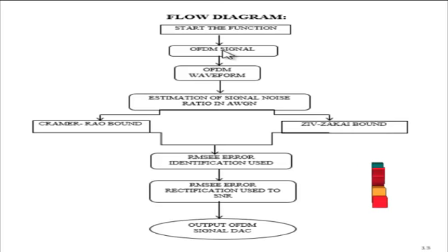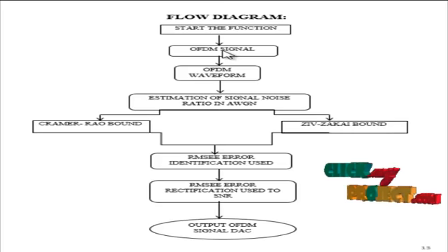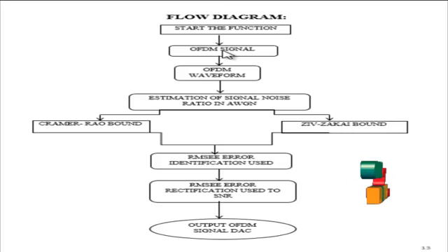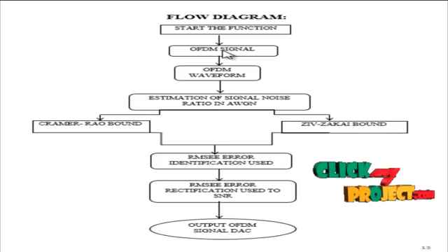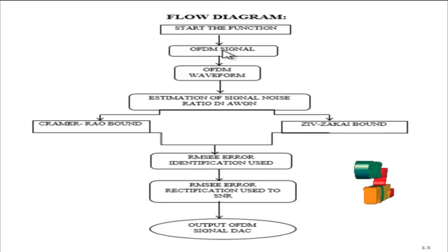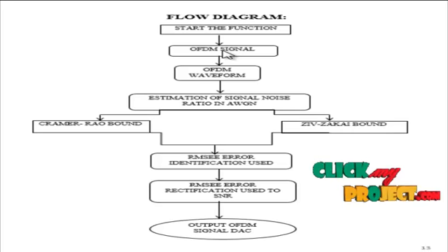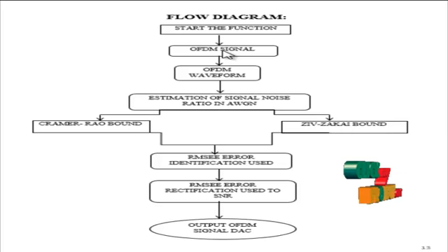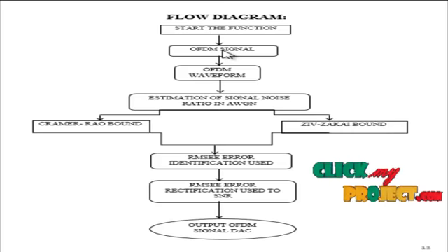The ubiquity of this communication technique has determined an interest in OFDM technology also in the field of positioning, where the intrinsic characteristics of the OFDM signal may be studied for understanding how to design a proper OFDM waveform suitable for pseudo-range calculation. Concerning this aspect, the estimation of the time of arrival of a signal is a fundamental topic.